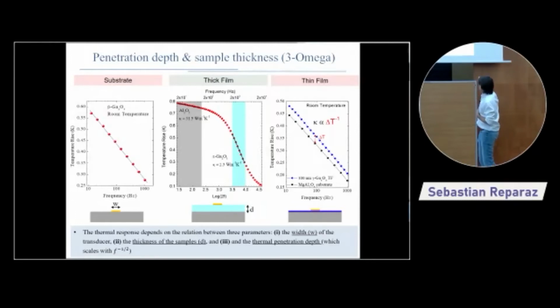And then when you put a thin film in a low frequency range, of course, what you end up having is a shift. And by just this shift, this would be completely analogous to the electrical case. By this offset that you see here, you can very easily obtain the thermal conductivity of the thin film. And this is what people are doing to measure thin films. Thickness depends, but under the order of 100 nanometers, this works really well. 200, 300 as well. Then if you go below 20 or 30, things are getting a little more complicated.